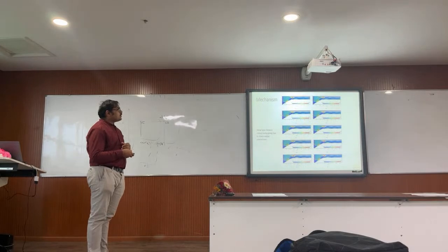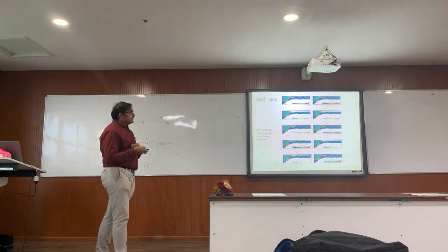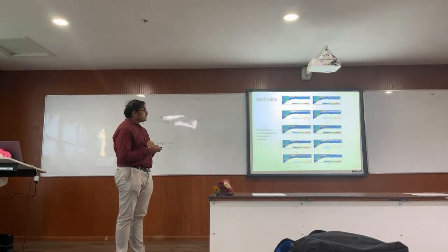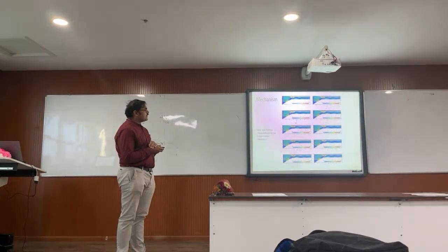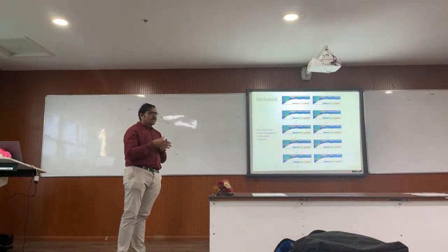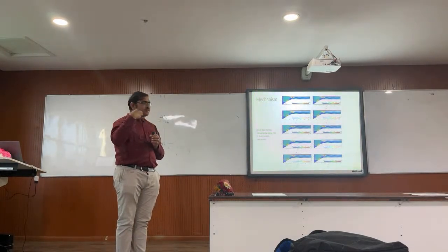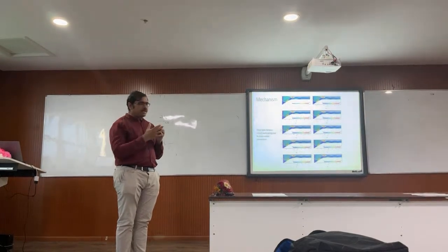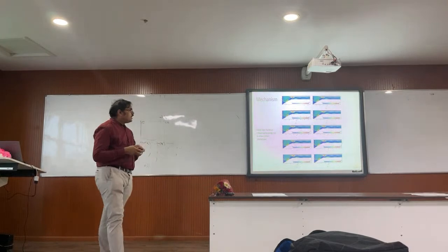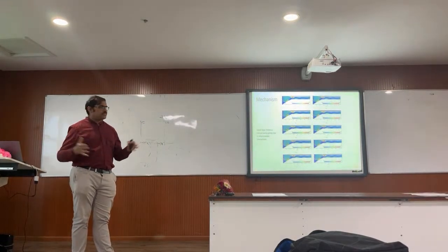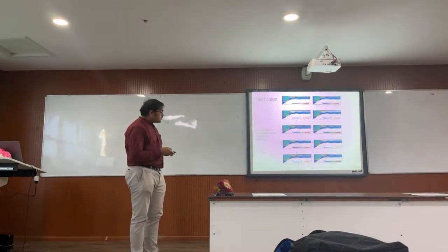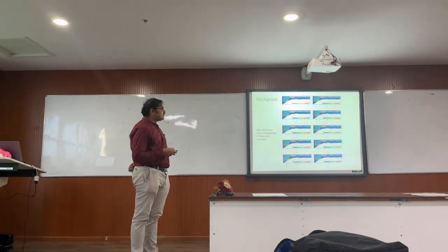Okay. So then we went on and found out why these oscillations are getting formed, and this was because of this shear layer impinging on this particular cowl wall over here. This actually generates a kind of virtual cavity, and if you have such a cavity, you can have a lot of vortices being produced over there, and these vortices sort of amplify in the cavity, and then it gets pushed out, and then again the system re-establishes. But these oscillations would not be very large in amplitude. So, this is the mechanism in these kinds of oscillations.